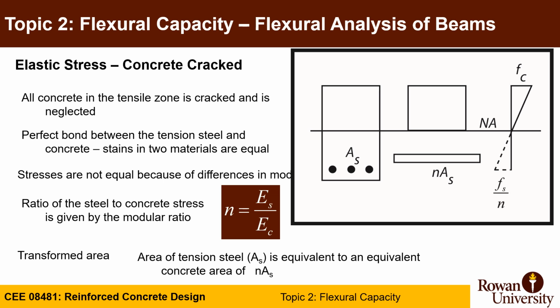Moving from cracking moment, or moment below cracking, our stresses below cracking, to stresses, actually elastic stresses, when concrete cracks. So in this we have some assumptions that you need to know. All concrete in the tensile zone is cracked and is neglected.